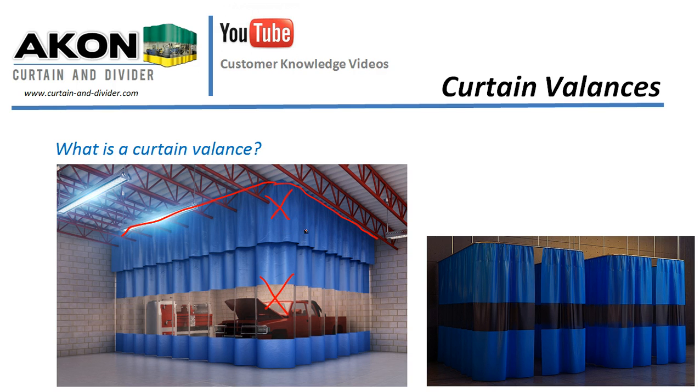The material is actually the exact same material as the curtain below it, and it's static in position. So you have the top valance, which is static, and then you have the bottom curtain, which is operable, which you can move side to side. So typically a curtain is installed like we see here. So you have your main curtains, and then above it, you have free open air. So these are great for welding, just forming work zones. But when you have to control the environment, either inside or out of the enclosure, then a curtain valance is ideal to seal that space up.